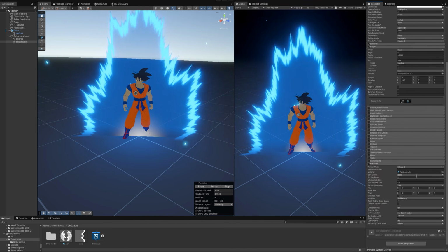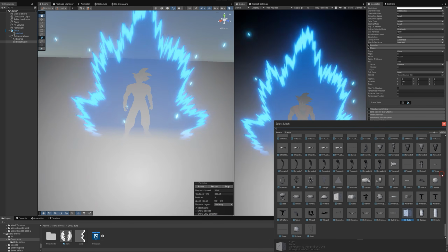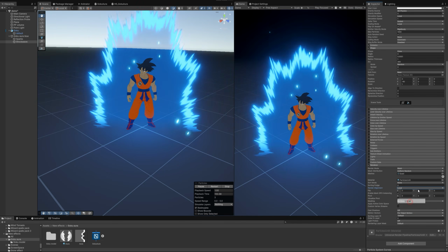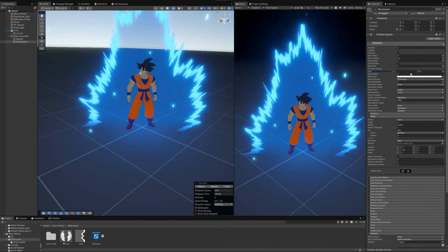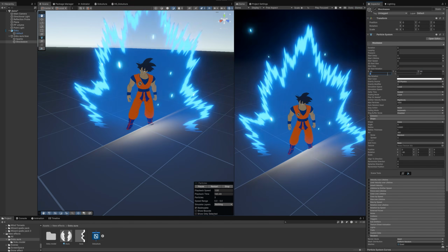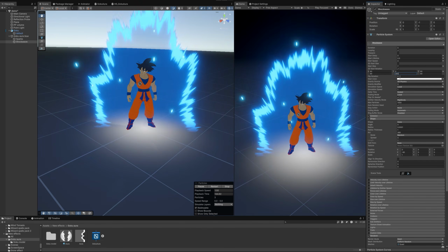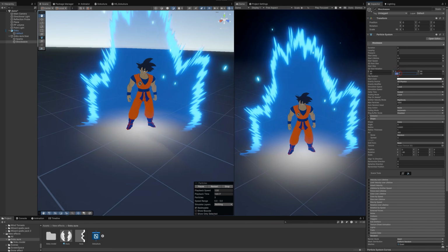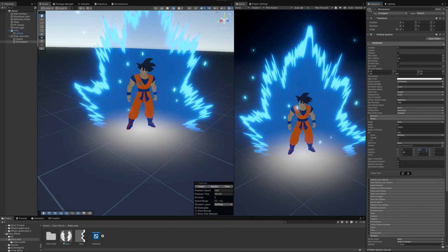Go to render, select render mode mesh, select cube, instead of cube set render alignment to local, and rotate here and here 90 degrees. Then set random between two constants and set the constant from 0 to 360 degrees, and move it slightly above the ground.